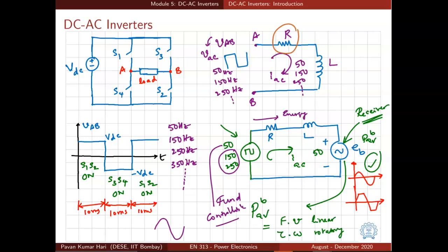As most of the motors have almost sinusoidal back EMF, we will be considering the primary objectives of our inverter as generating an AC voltage with a controllable fundamental component, and with as few harmonics as possible. These two are the main objectives for our inverters to achieve.